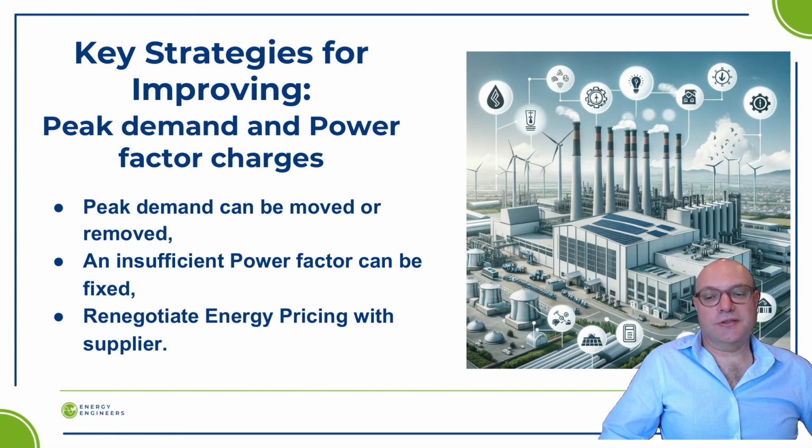Another fix is the introduction of variable speed drives. The power factor of a VSD is usually better than an electric motor, especially those not running at full load. Another option that you can look at is renegotiating the peak demand and price of energy with your supplier, and/or moving to market pricing based on energy suppliers such as Energy Locals and Amber Energy.